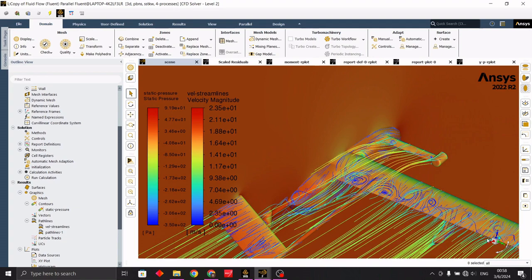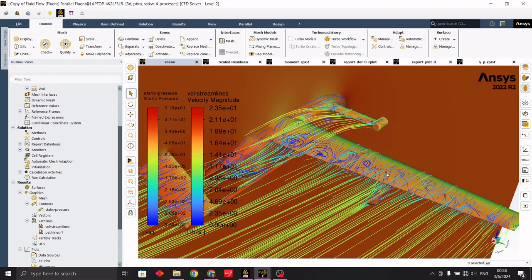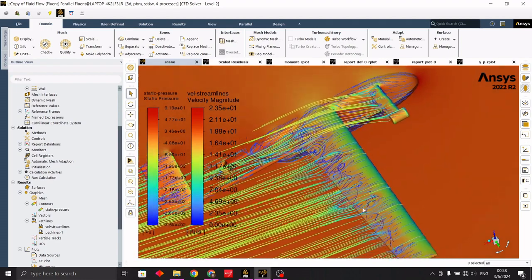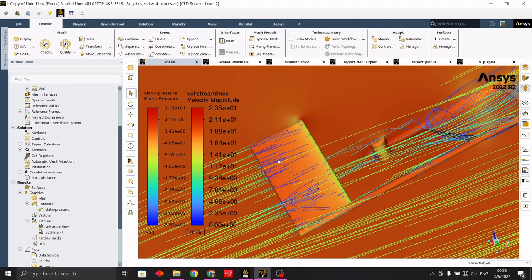This may be a bit of an issue, since around here is where our aileron is expected to be. However, at least this also shows that for our tail, the flow is still attached, which is good, because for us in this case, the rudder and elevators are the most important things in terms of recovering from a stall.